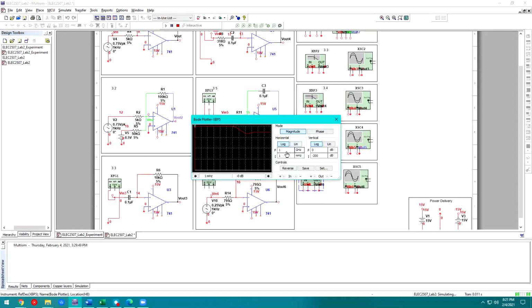And you should see the magnitude and phase as a function of frequency, right? So go ahead and increase the vertical scale so you'll just see a little bit above the 0 axis. And we'll go ahead and limit our bandwidth again. Just limit it to maybe just that region, right? Because we want this nice passband that goes up and up and up until our cutoff, and then we start to drop. So I can see my 3 dB frequency is right where I calculated it to be.